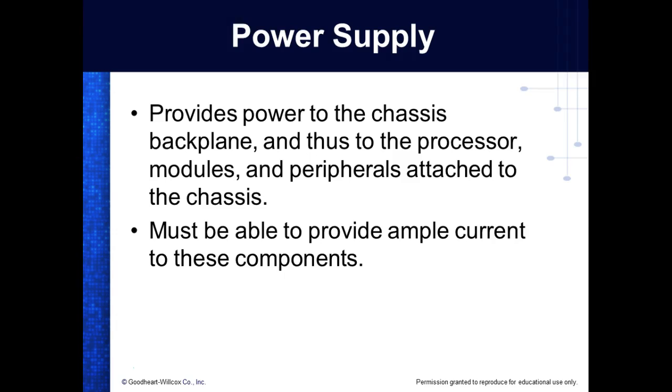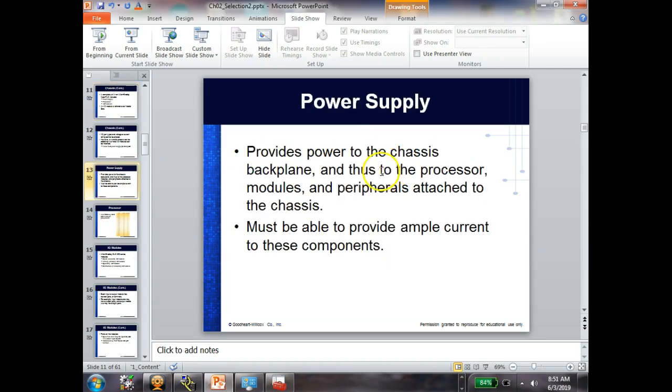Power supply supplies power to the chassis, backplane, and thus the processor, modules, and peripherals attached to the chassis. Peripheral, what's a peripheral? Outside the computer, right? But you're not going to hear this term much out in the field. Most people out in the field call these field devices.